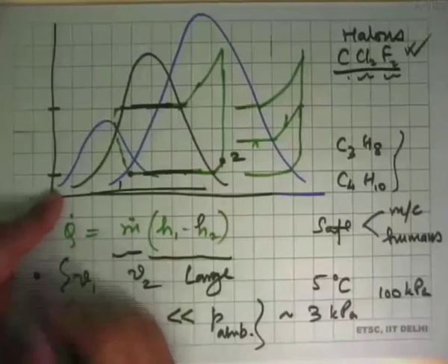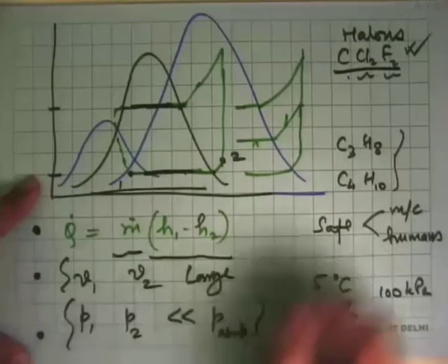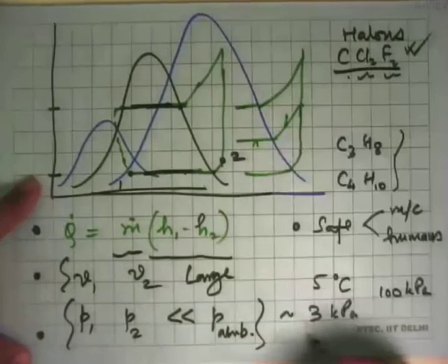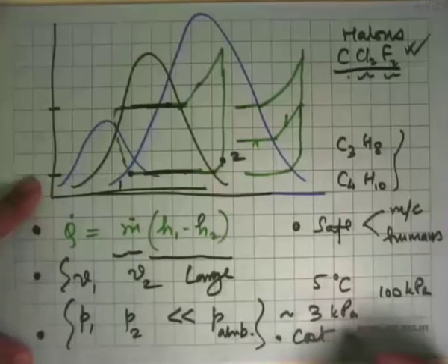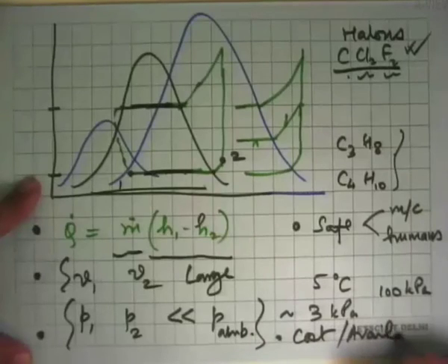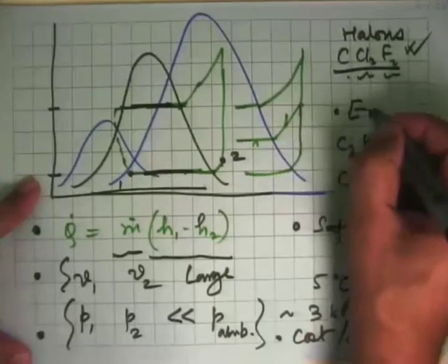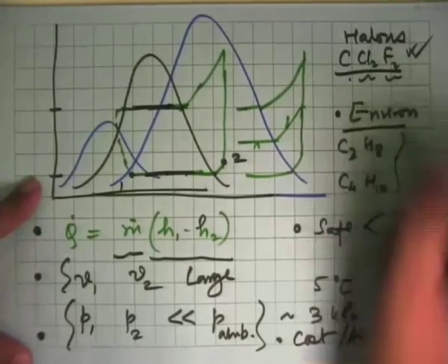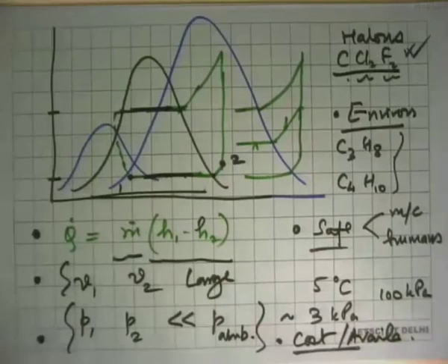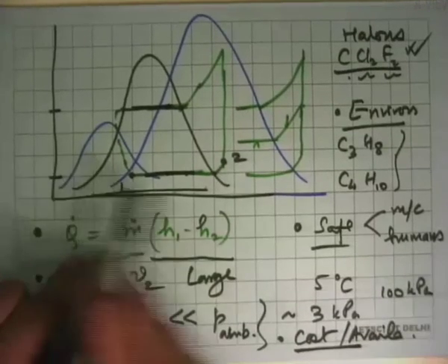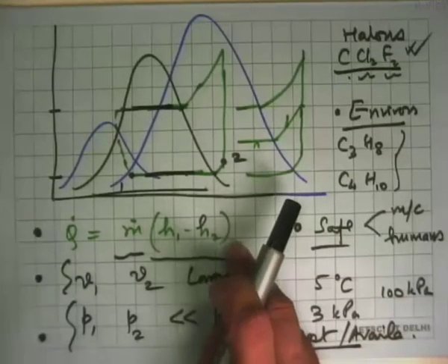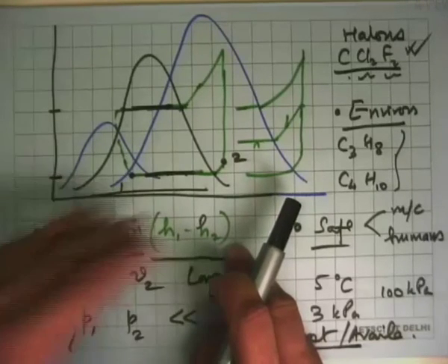Specific volume was another criterion. Then we look at heat transfer rate, safety, and then, of course, as an engineer, you always have to worry about cost and availability. And these days, like it started off this whole thing, environmental impact. So these are many issues that decide which substance to use in the refrigerant cycle. But the starting point is that you say, well, does the thermodynamics make sense? If the thermodynamics makes sense and the engineering is doable, then that becomes the candidate material for the next step of consideration.